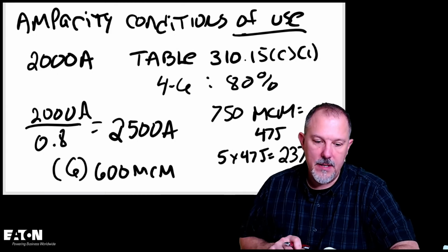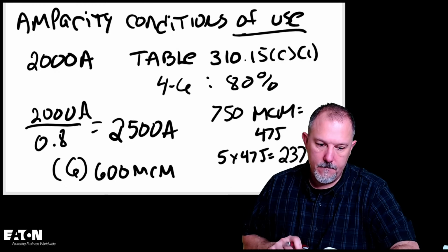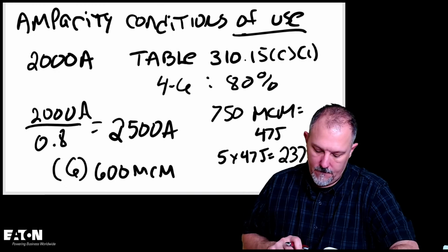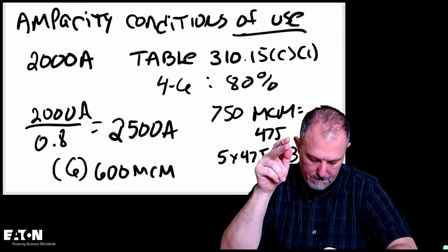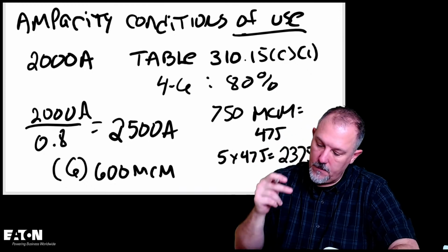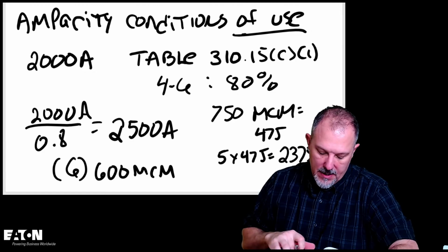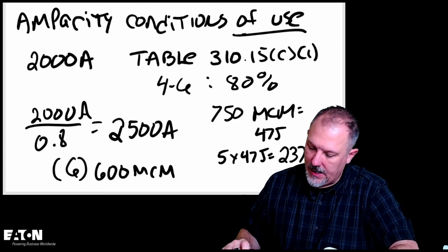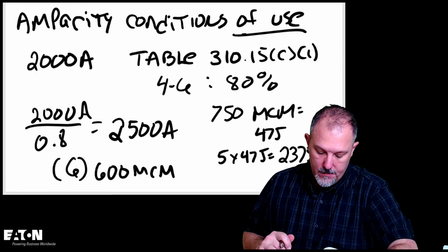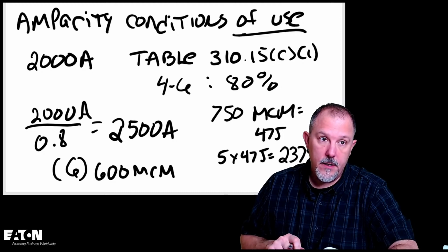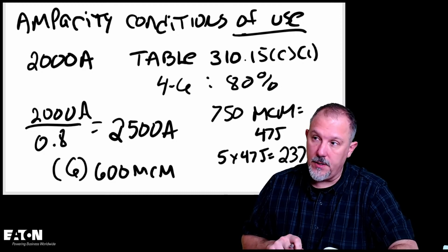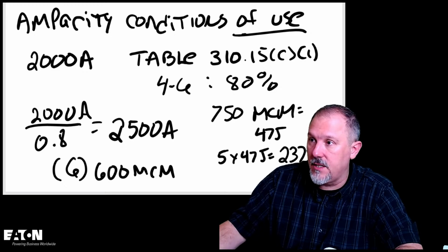Yeah, but I'm limited by the... Something doesn't smell right, Ryan. So I know I need 2,500 amps. If I use my 90 C column at 750s and do 5 times 535, I'm good. I'm good to go. So that should be good. I don't have to change this.